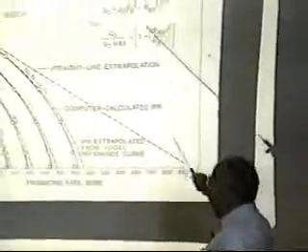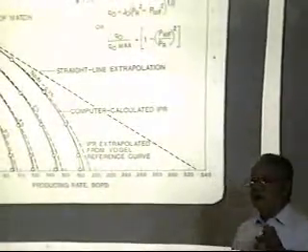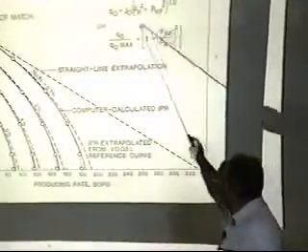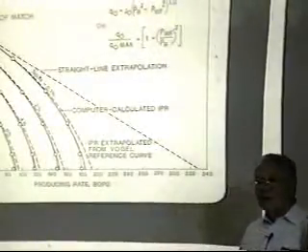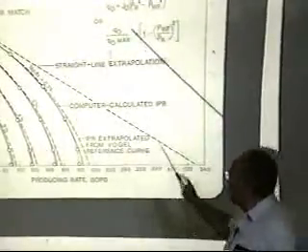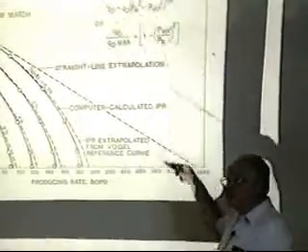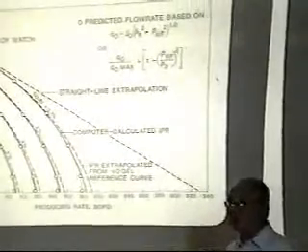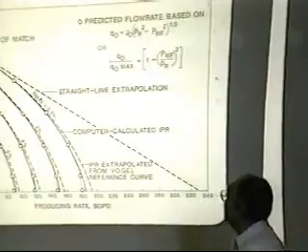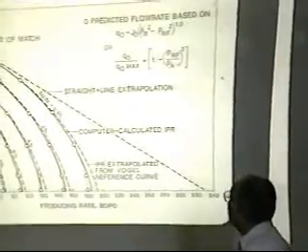In this form, see, I dropped the 1 term, and the coefficient becomes 1 for the squared term, and the other coefficient becomes 0. Now I have a back pressure equation where, like I said earlier, the rate's not strongly a function of the level of the flowing pressure that I'm going to choose. So that's one advantage that I have in knowing it behaves like an oil well, or like a gas well.